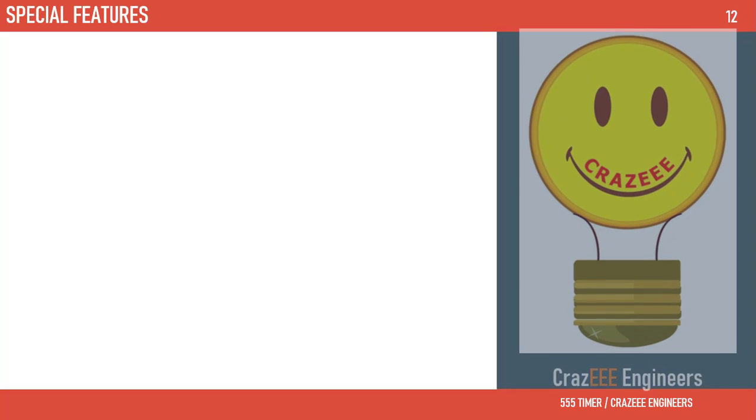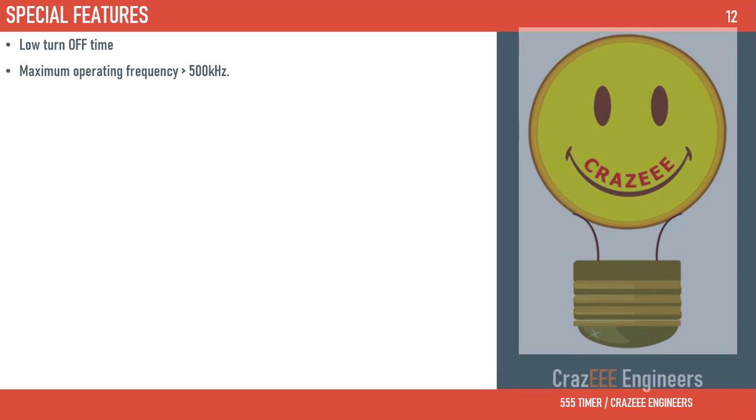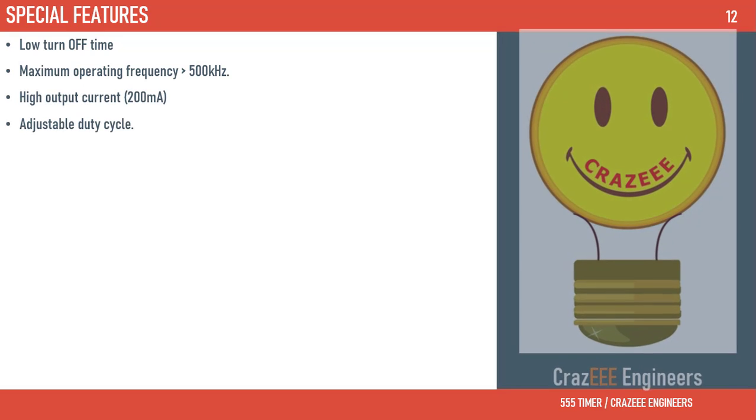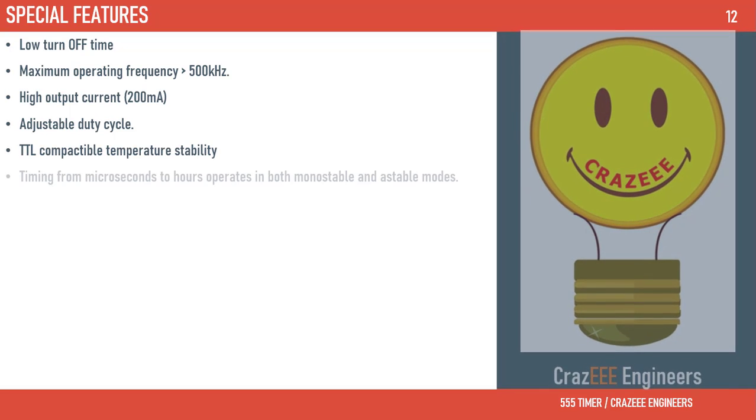Special features. Low turn-off time. Maximum operating frequency greater than 500 kHz. High output current, 200 mA. Adjustable duty cycle. TTL compatible. Temperature stability. Timing from microseconds to hours, operates in both monostable and astable modes.